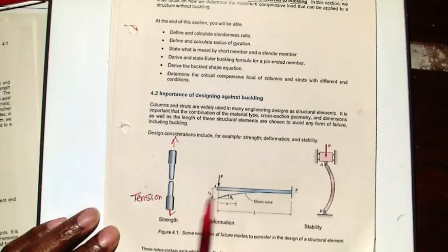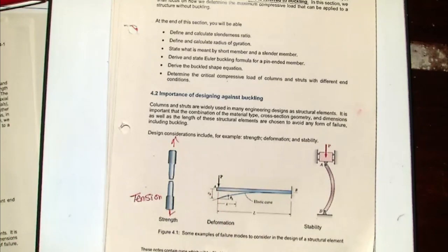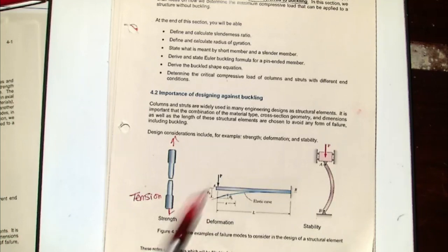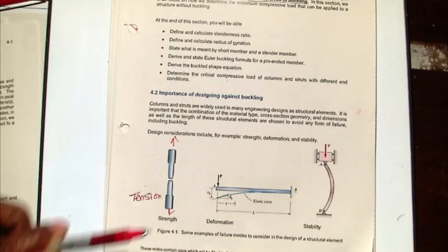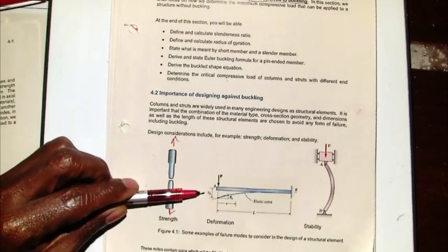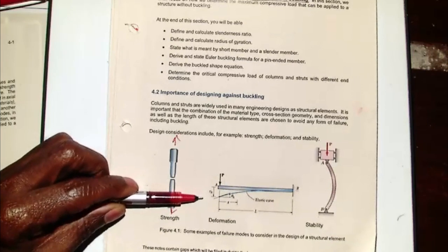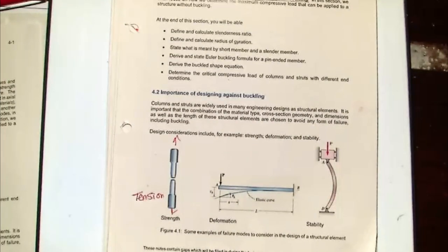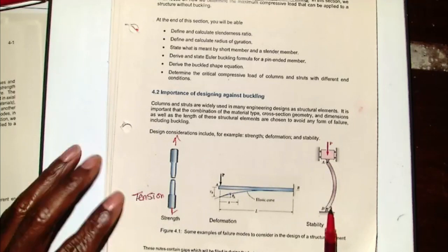And the one that we've just been doing is something like this, where you have a beam with a load applied in the transverse direction, and it will basically deflect. And we are trying to find what is the maximum load you can put in. Now we can find the corresponding maximum stress that will be developed in the beam and relate that to the maximum load we can put on the beam. Sometimes it's the deflection that is the main limiting design from what we've just done. If you have a maximum value of deflection that you do not want to exceed, you can work out what deflection your given load will give you and decide whether your given load is within the level that you want it to be. But what we'll be doing now is something like that.